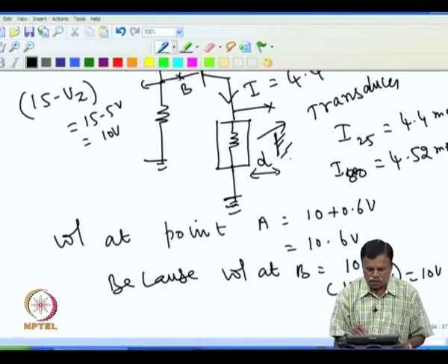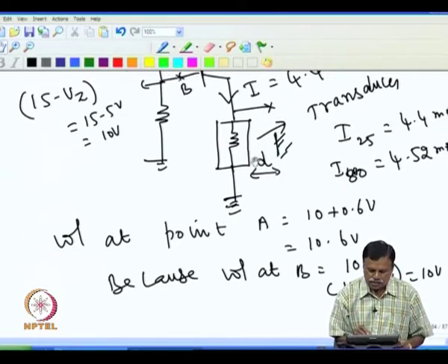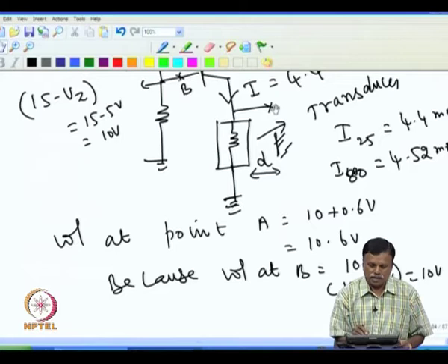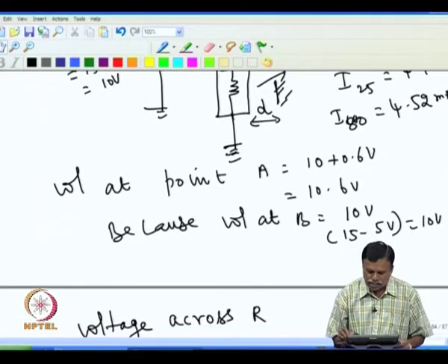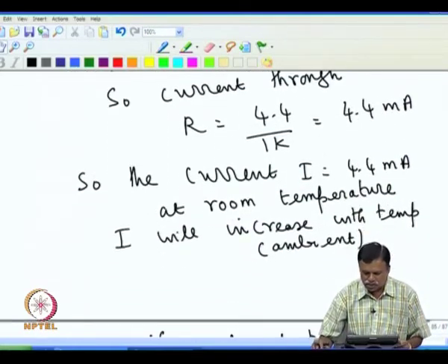If the distance increases, the effective resistance is supposed to decrease, but assume that this resistance changes with temperature also. Assume here it is decreasing with temperature, then the voltage at this point will decrease with temperature. Now, the increasing current will compensate that loss. One can select the proper values of R to get whatever compensation is required.